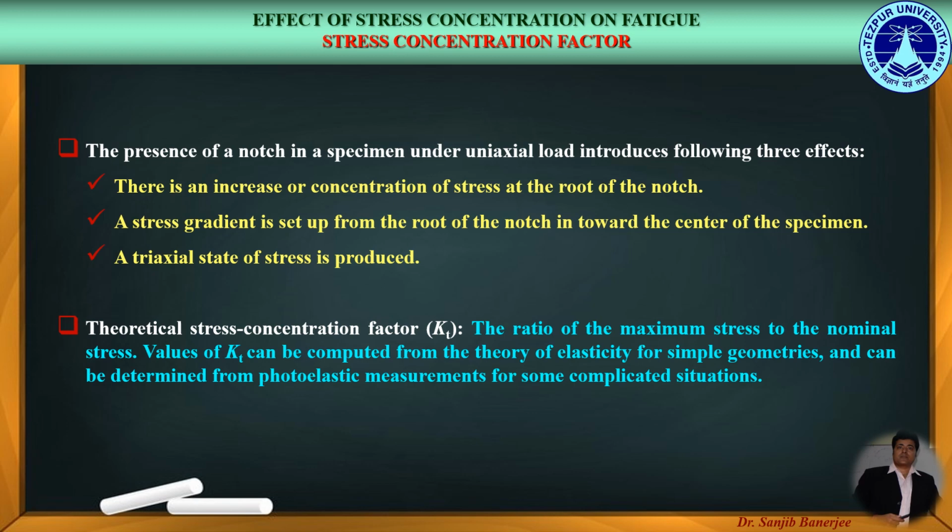Firstly, due to the notch, there is an increase or concentration of stress at the root of the notch. Secondly, a stress gradient is set up from the root of the notch in toward the center of the specimen. And thirdly, a triaxial state of stress is produced.